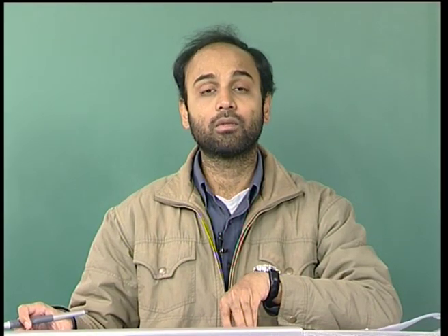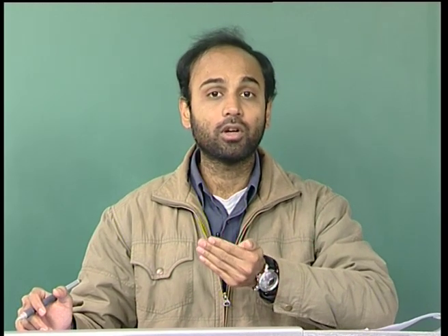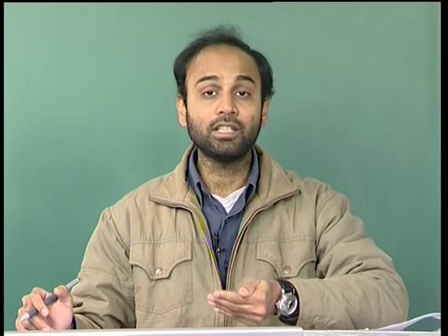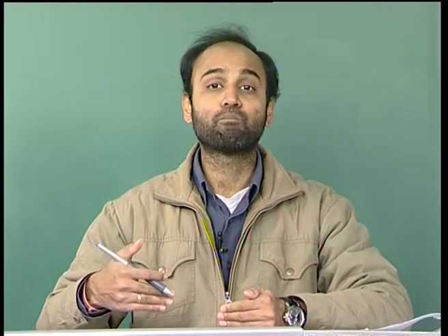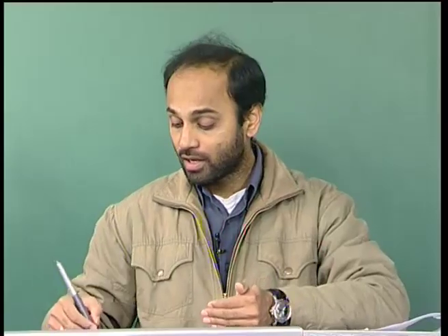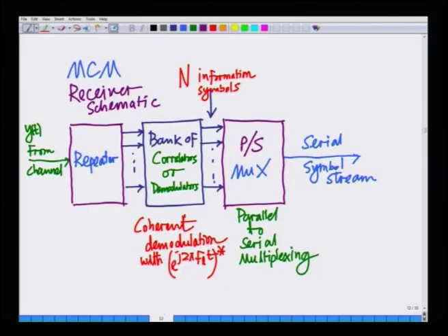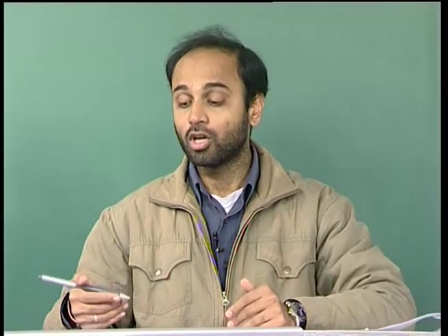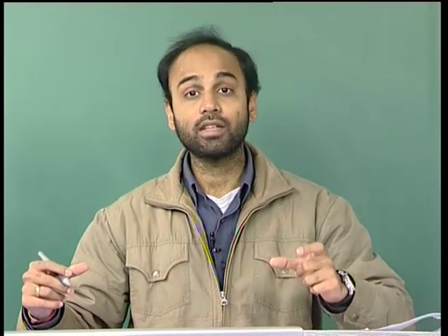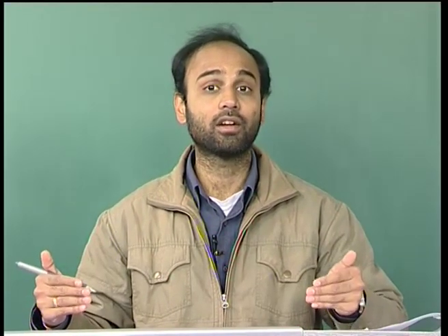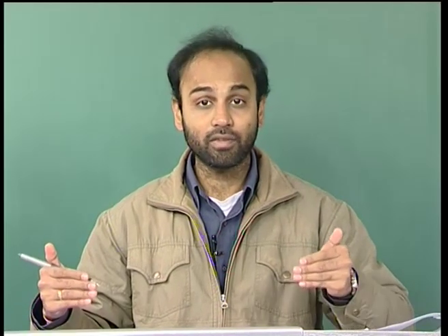Conventionally, in a single carrier communication system, I need only one modulator, and implementing that one modulator itself is significantly challenging because a modulator implies I need an oscillator and so on, and these oscillators have to be precise, as in the frequency and phase have to be precise. In fact, at the receiver also the oscillator has to be matched in phase to the transmitter oscillator, otherwise you will have phase offset and so on. So, implementing even one modulator and one demodulator is a big challenge. Now, we are saying in this N subcarrier system we have to implement N equals 64 modulators or 256 modulators. So, the number of modulators and demodulators scales proportionally to the number of subcarriers, which is extremely challenging, and the amount of RF hardware required is not insignificant. It is a fairly challenging task.